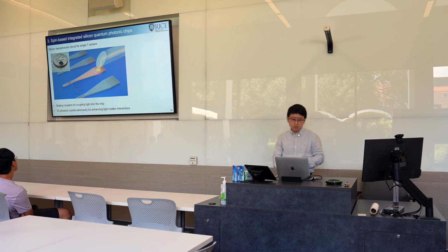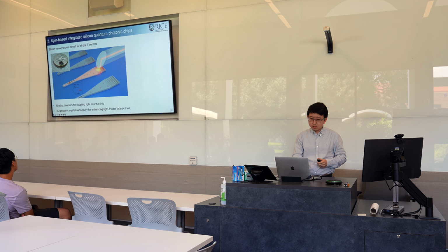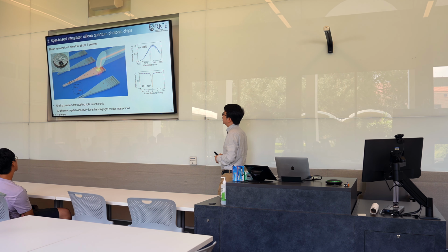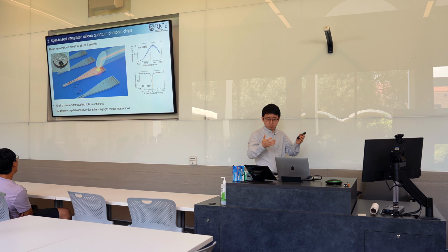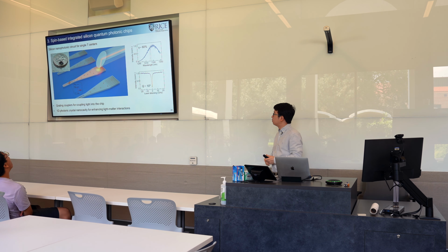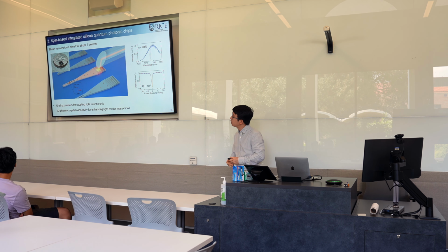Okay, so that kind of colorful line, that's the diffraction color in the room light environment due to the grating coupler. So the grating coupler can perform very well. The one-way coupling efficiency can reach about 60%, which is relatively high. And then the Q factor of the device can reach about 100,000.